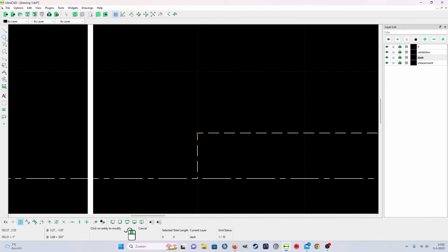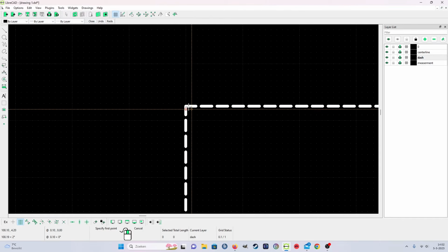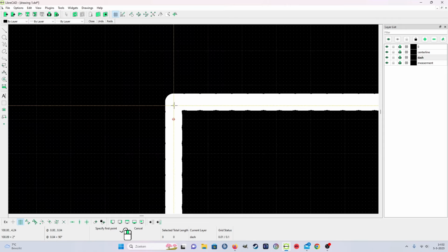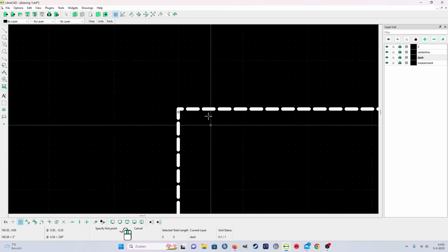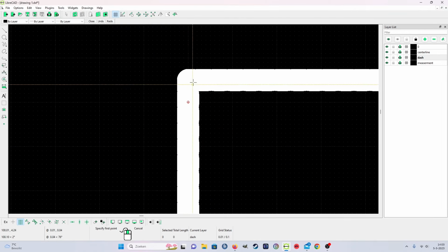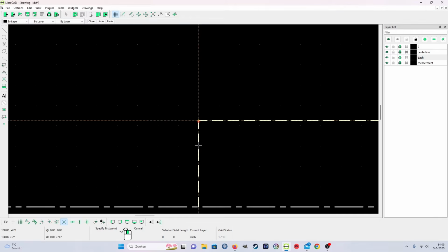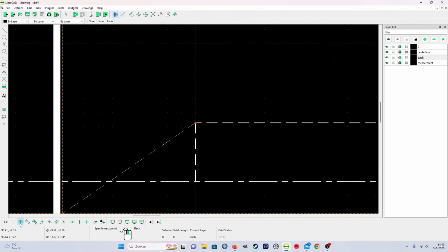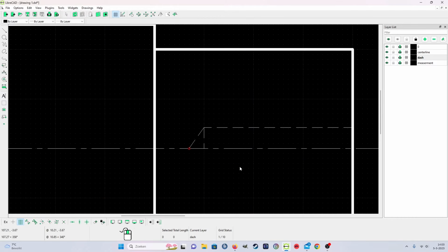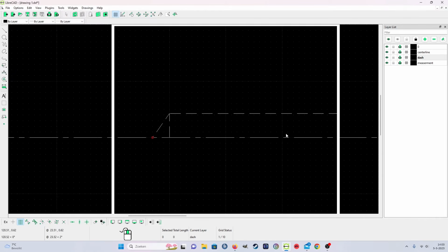Now I'm gonna put the drilling point on. You see what I mean? I must zoom very far in now to get to the exact point. But if I do this again, and I do the snap, then it goes automatically to here. And when you select the point, put the snap off and put the grid on, and then you can put the point where you want it to have. So that's my drilling size.